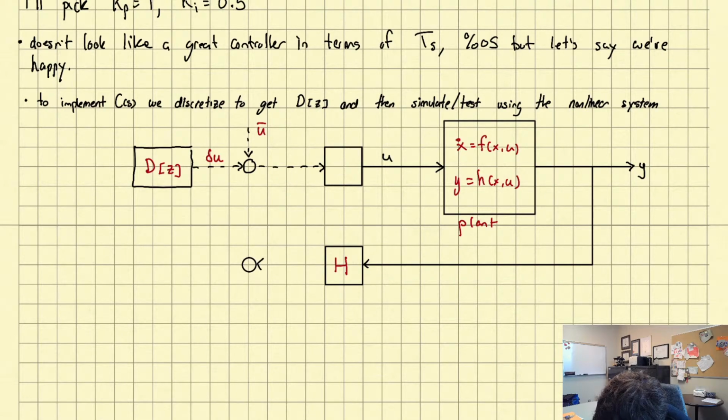Oops, I think I've got these backwards, sample and hold. Sorry. So the idea here is you measure Y from your sensor and you subtract the pre-computed value Y bar, right? This is where you did your linearization at.